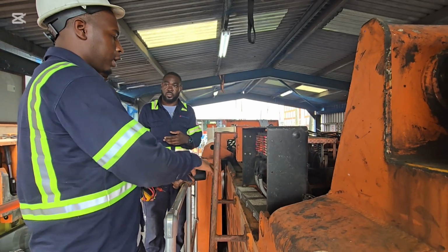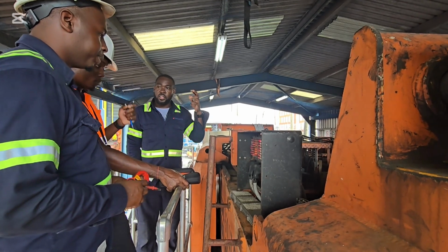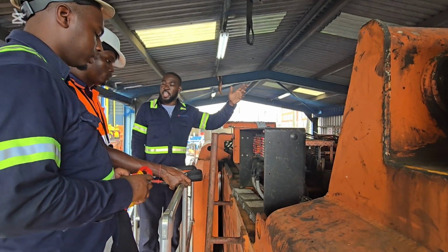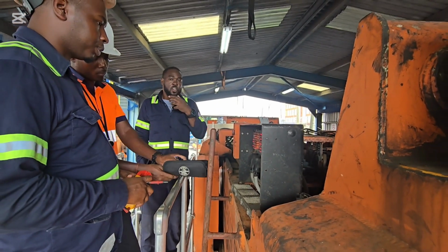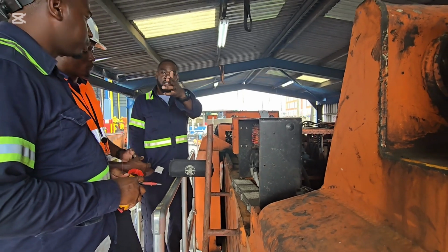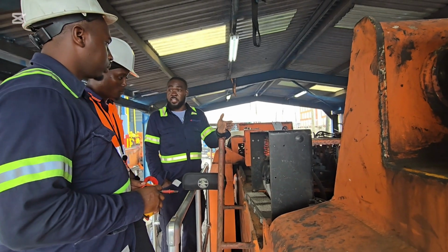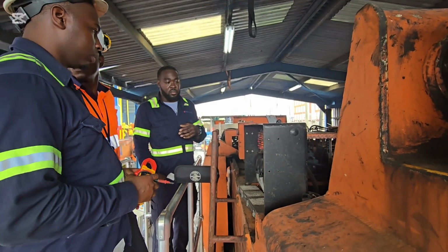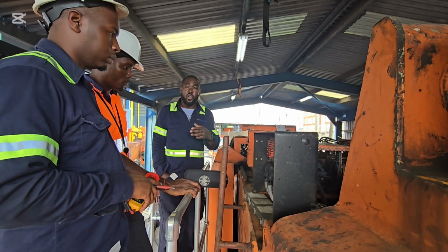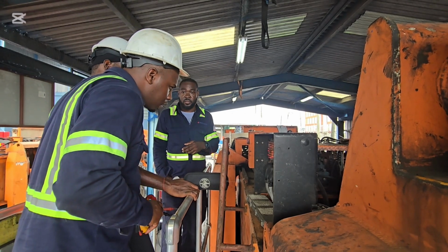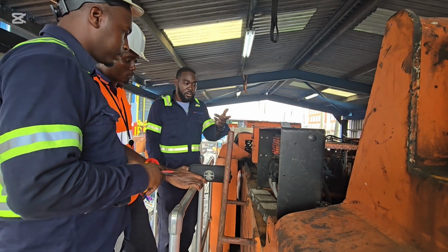Just checking the function block and checking the release. Just make sure that we're getting the proper output. Alright, great. And what is step 3? So apply. Alright, so you identify flipper not going down. You ask the questions, gather information. Now we're going to apply a solution. What is the solution in this case? A relay is missing. Alright? So can we find a relay and put it in place?